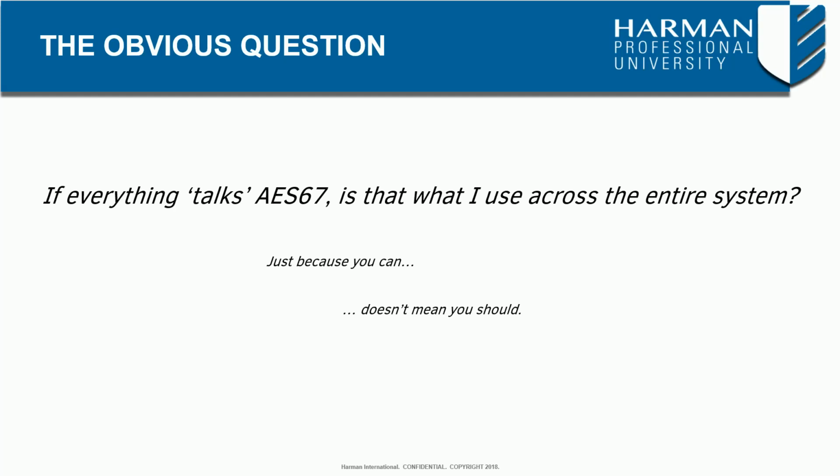Also keep in mind, while AES67 aims for latency targets less than 10 milliseconds, if we must guarantee a latency of 5 milliseconds, then it would be wise to continue using one of the other audio transports that allows us to configure that setting. It is only when communicating between systems with different native transports that AES67 should be used as a common transport or bridge. This approach allows rich transport-specific functionality within the subsystems, but facilitates a more basic audio connection between subsystems when necessary.